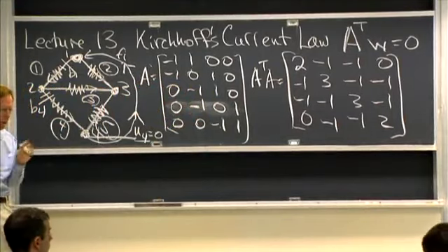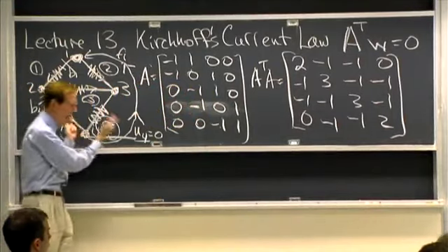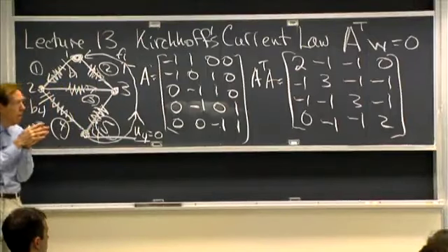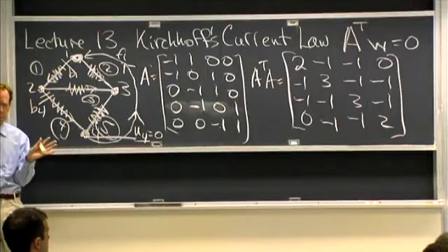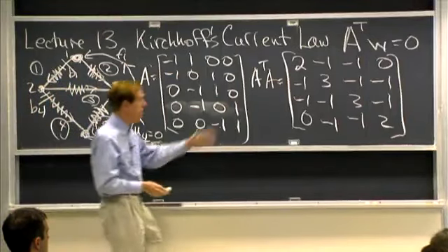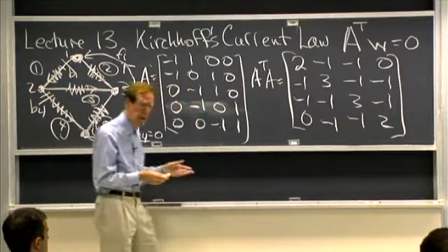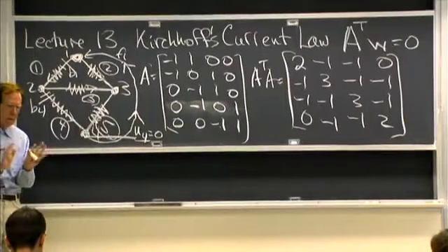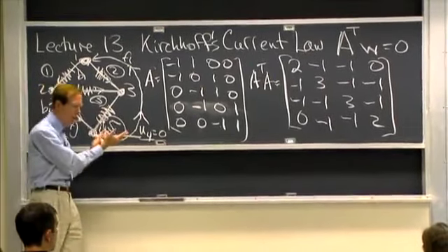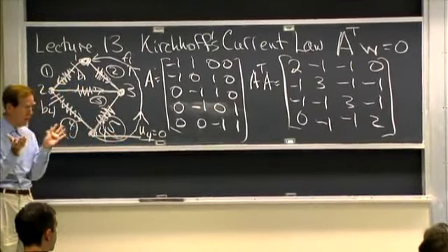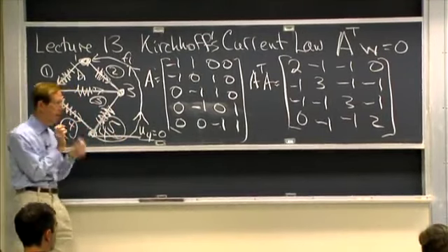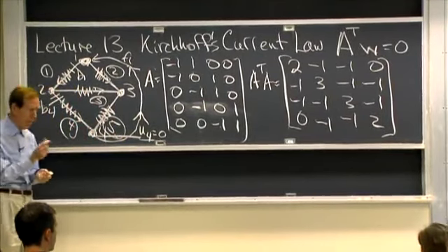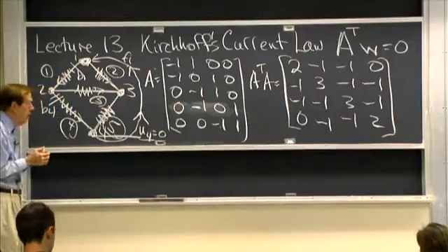just a small comment, that we'll have exactly the same thing in so many other applications. In big finite element codes, you produce a stiffness matrix that's initially singular, and then you impose boundary conditions. That's the efficient way to do it, is create the matrix first. That's the big job. Then impose the boundary conditions. That's the small but occasionally tricky part.